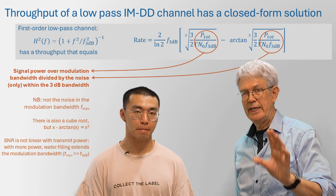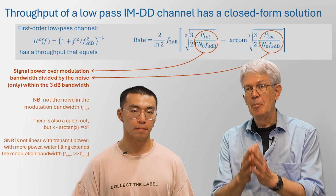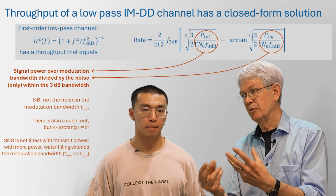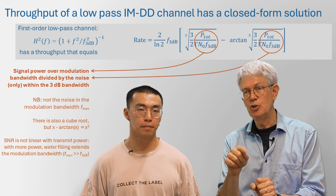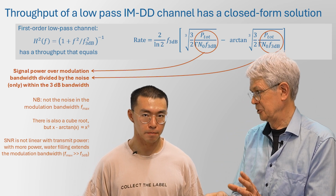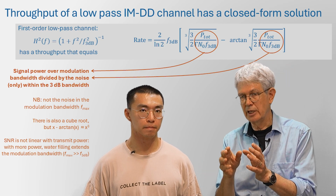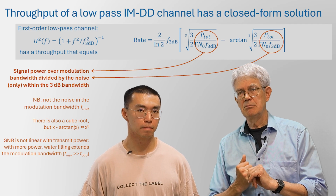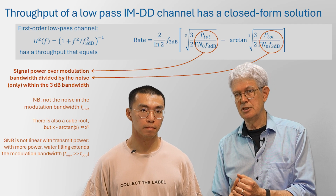So then we have the rate is proportional to the bandwidth of the channel. I can understand that effect, although it is not the bandwidth of the modulation, but the bandwidth of the channel. But that's what the mathematics says. And then we have the cube root of power over the noise bandwidth of the channel, times the arctangent minus the arctangent of the cube root of that argument. Still, it looks a little bit hard to interpret this equation.